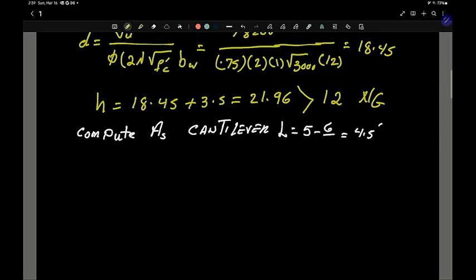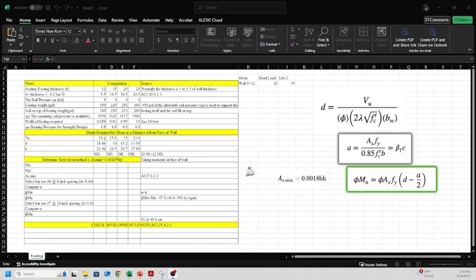All right, the next thing we're going to do is calculate the area of the steel, and there are a number of ways you can do it. There's a table you can use, which basically gives you the correct steel, or you can use Mu divided by 4d. That's kind of high, but it will do the work. Or we can go ahead and follow the ACI, start from a minimum and work our way up. Let's go use the ACI method.